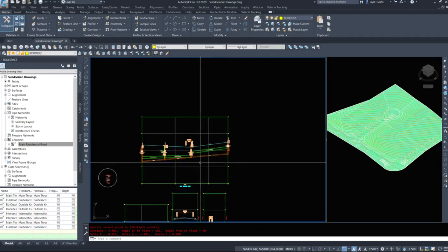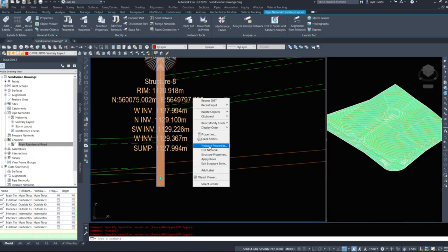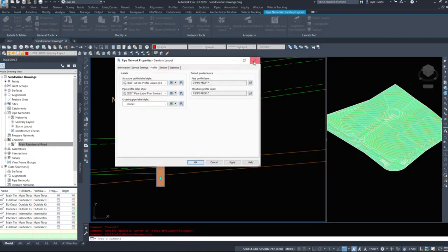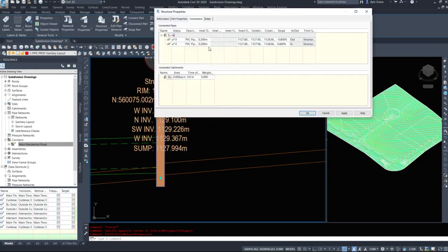This will be the only spot in our subdivision where the pipes would actually interfere. However, if you have a larger subdivision, you're going to have more crossings, more interferences. And it's not just the storm pipes that we have to worry about. It is the water pipes as well. So when we get into the pressure networks, we're going to see how those interact, and how we can make those go up and around and do specific things for us.